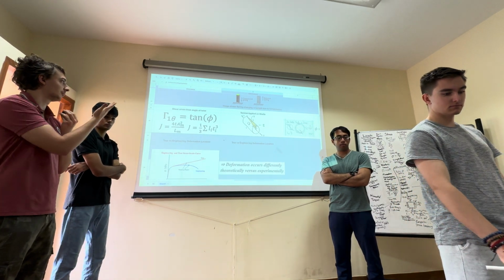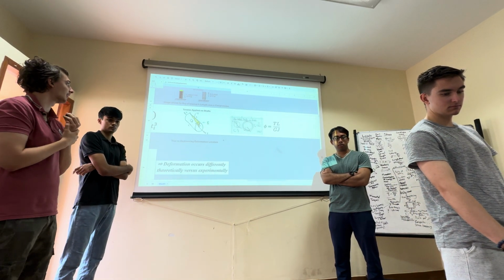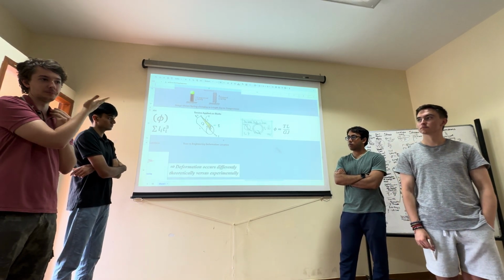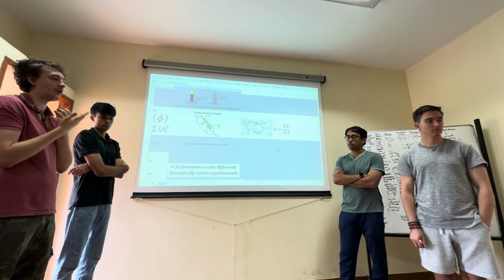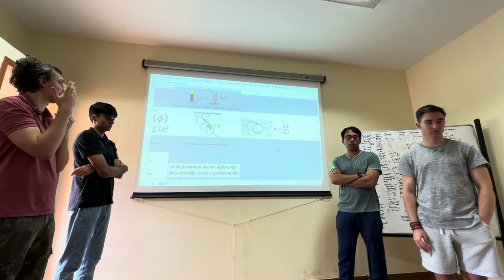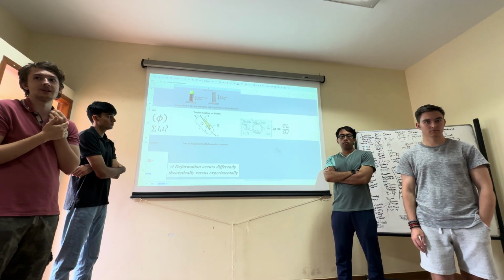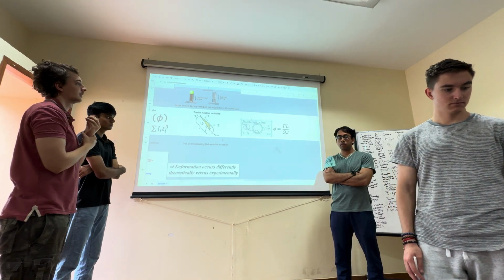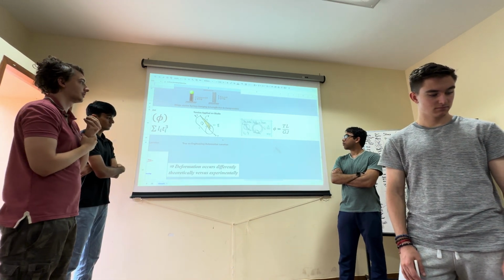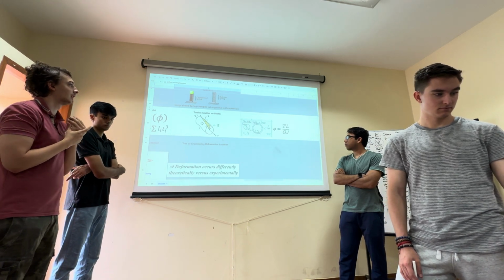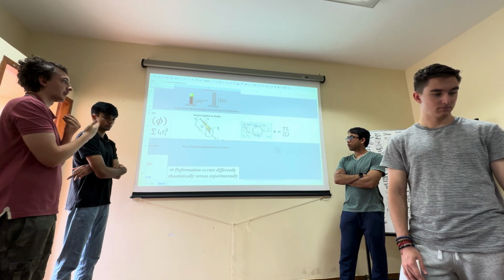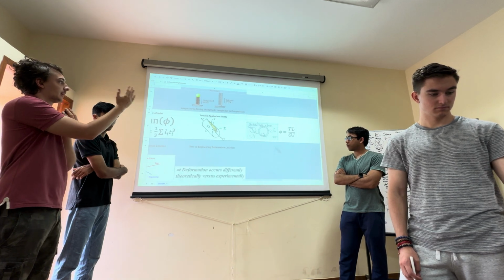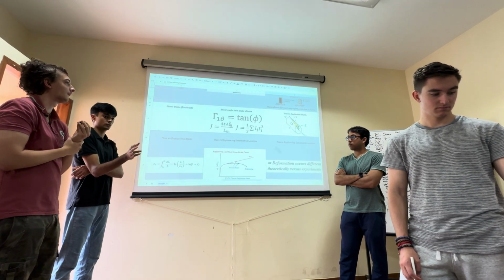And also earlier, Matt mentioned other torsional coefficients, also based on geometry, like there was for beams, for specific holes in an object. So yeah, those are extra values of J that also depend on geometry. And at the end, we have the final equation that relates the deformation all the way back to loads. As we can see, it uses torque in the equation to find the angle by which the object twists.